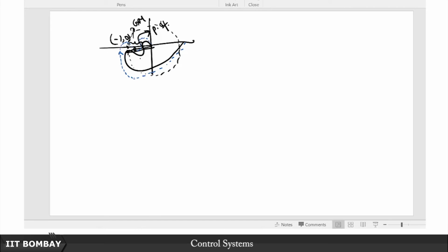So therefore be very careful, do not just look at one of those metrics and infer about stability or stability margin, look at both of them. For a good closed loop stable behavior, you would ideally want good gain margin as well as good phase margin. If you just have one of them to be a reasonably decent positive value and the other is pretty bad, well then you should be alert, because there can be these nasty sort of things that might be going on.